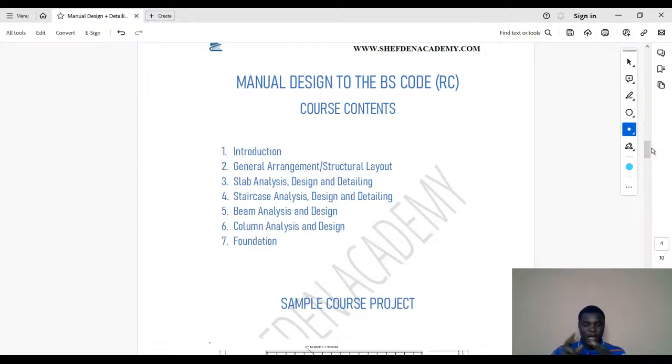So you learn about how to analyze your load from the start, how to apply the loadings on the slab, and then how to analyze the slab. Once you finish the analysis, you learn about design of the slab, that is to the BS code. Then you learn about the detailing of a slab, like detailing the whole slab individually. Most of the software we have usually gives us details, like Prota Structures, ETABS, and the new one that we have now, Revit, which can also provide reinforcement detail.